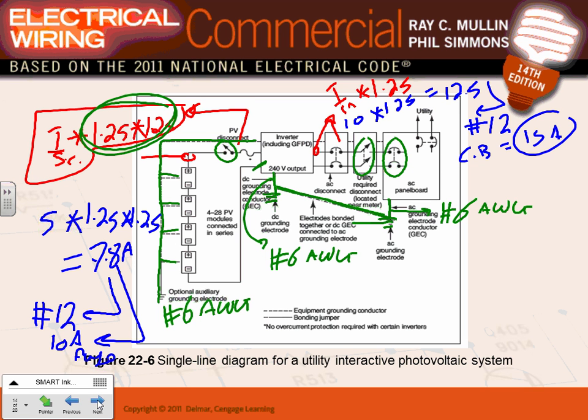Any comments, any questions about the one-line diagram for the system? And then all THHW wires. THHW wires, wet location, absolutely, typically. On the AC side, if you're inside, you really can't get away with THHN. If you're inside, it depends where you are. Typically, you're coming from outside to inside, wet location, THHW. Absolutely. Really straightforward, no gimmicks in that system.